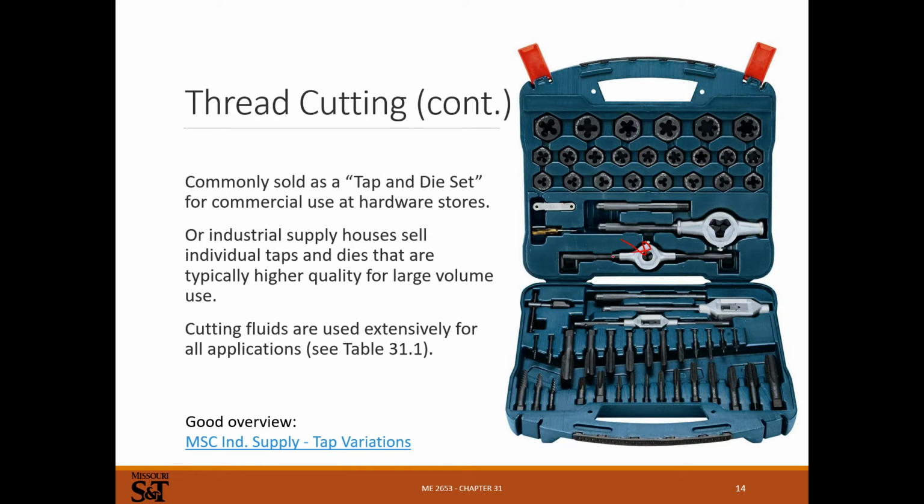The handles like this, I basically want to throw away. They don't hardly work. I don't know who makes this. This might be a decent one. I don't know. It doesn't look decent to me though. I really like using this style of tap handle, and I like using good ones. Starrett makes really good tap handles for that. This style, after you've got threads started and you need a little bit extra torque, they work, but you need to buy good ones because the bad ones like this end up causing more trouble and breaking taps.